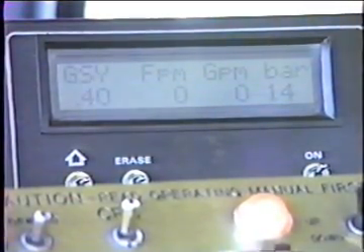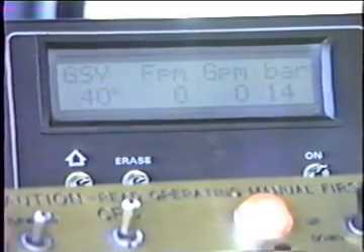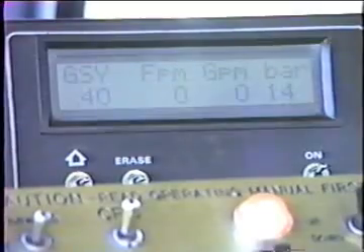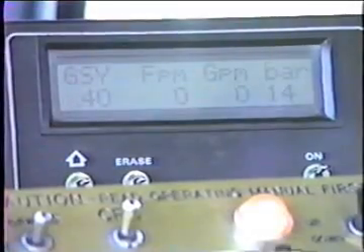Of course, people thought things were broke down then. Well, it wasn't broke down, we just didn't have any footage information to it. It instantaneously saw 0 feet per minute and decided that at that speed it needed 0 gallons per minute, and that's just exactly what it did. De-stroke the pump down to 0.